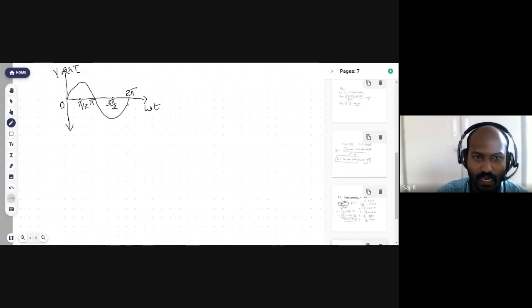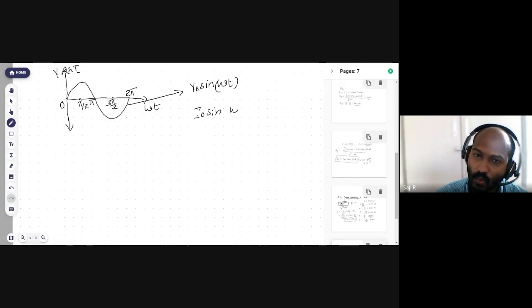This is the standard equation of the voltage applied across an AC circuit containing an inductor only: the applied voltage is V0 sin omega t. Now I am going to draw the current flowing through an AC circuit containing an inductor only. The standard equation for the current is I0 sin(omega t minus pi by 2).